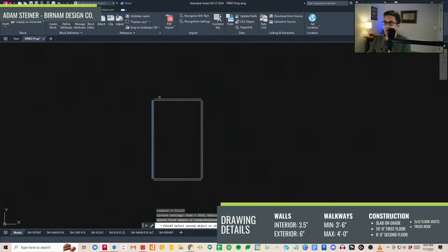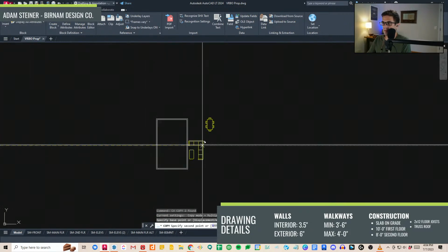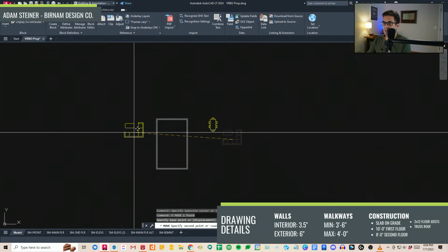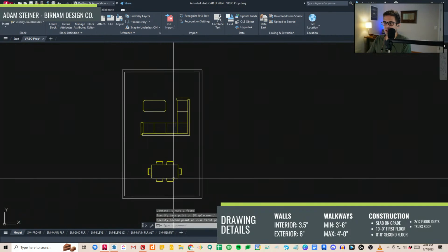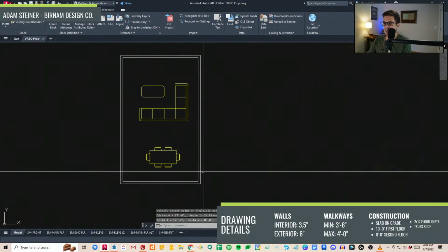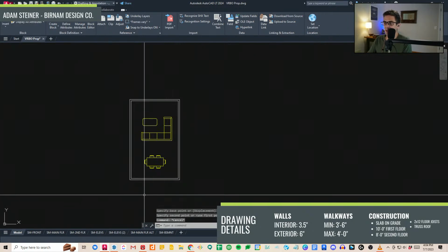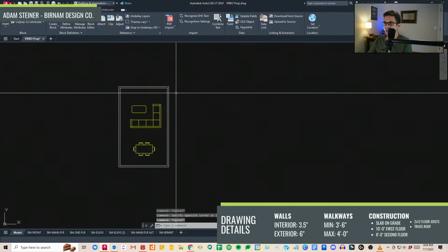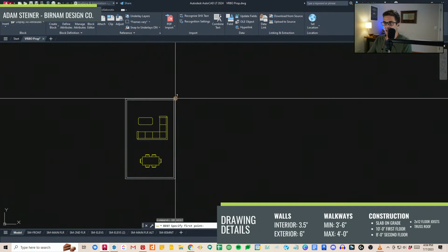Okay, and this block will be our dining and great room. I'm going to grab some furniture so we can help visualize that. Great room, dining. Why 17 feet, you ask? If I stick at 17, it's easier to do for bearing, to do 2x12 joists. I might play with that though if the joists are going front to back in this, which it looks like they might, so I could maybe sneak this a couple feet wider. Actually, yeah, let's do that straight away.